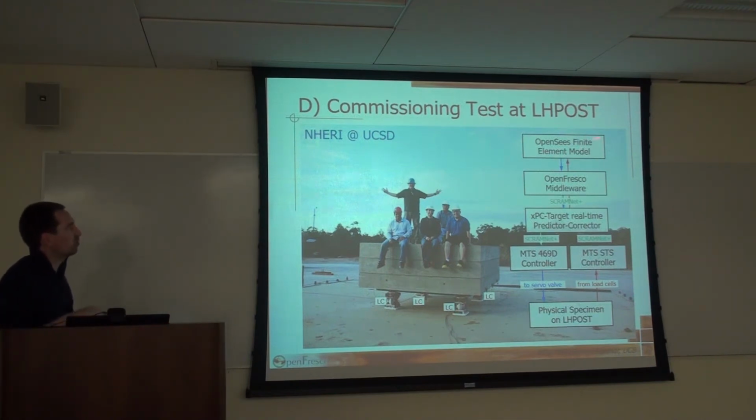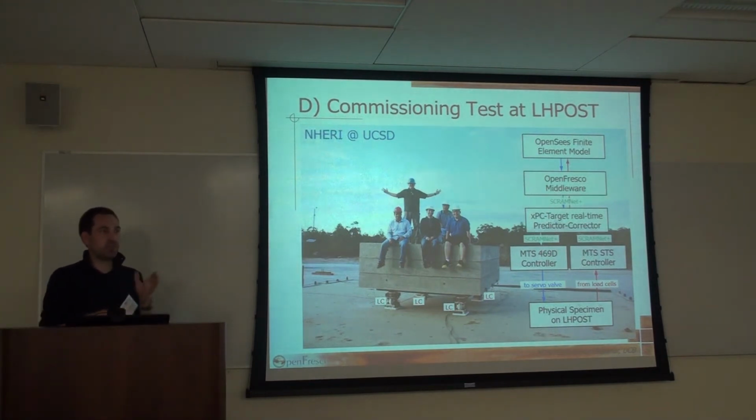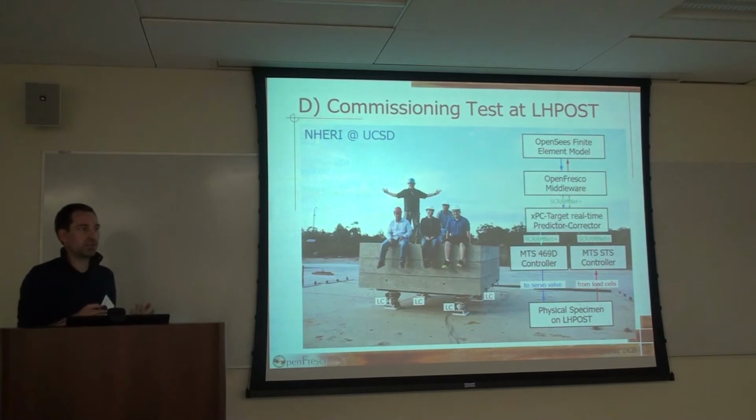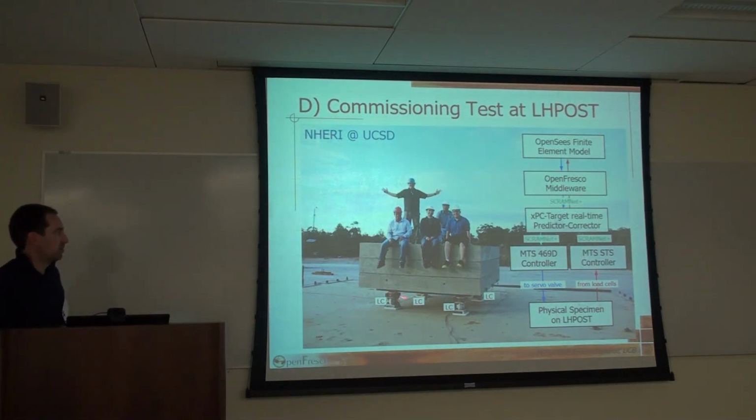The approach that we took was similar. We actually shipped our specimen, meaning the isolators and our load cells, from Berkeley, because they didn't have load cells. The steel plates, all that was shipped from here, because we wanted to try to repeat the exact same 1D test that we did here, so we can compare results. The blocks were a little hard to ship, so they cast their own concrete blocks, but the same weight as what we have here. And this will be exactly what we're going to see in the demo this afternoon.